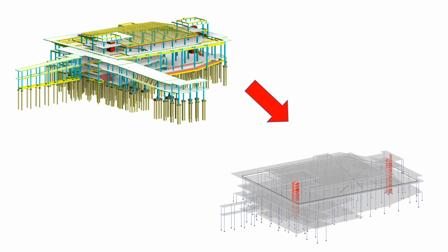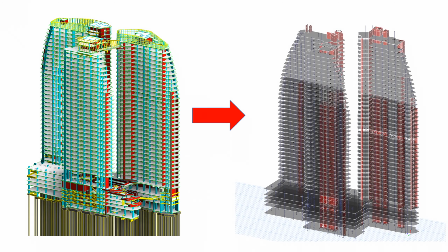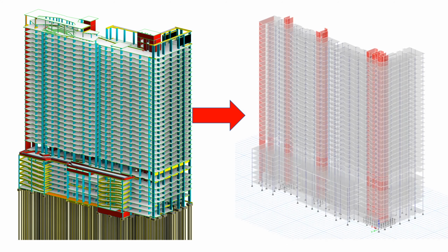Directly converting a Revit model into a finite element model without proper preparation will often lead to mistakes in the finite element model, such as unconnected nodes or unintended structural behavior. And to fix such problems manually later on is difficult and expensive.